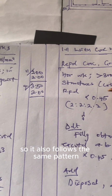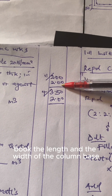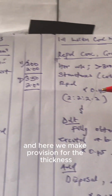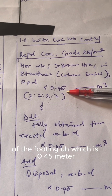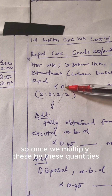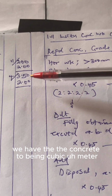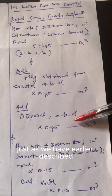So it also follows the same pattern. All we need to do is to book the length and the width of the column base. This is for base 1, we slash by 11, and this is for base 2, we slash by 4. And here we make provision for the thickness of the footing, which is 0.45 meter. Once we multiply this by these quantities, we have the concrete in cubic meters. We also make the deduction and addition just as we have earlier described.